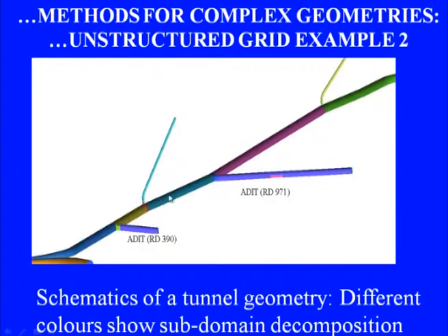And when we generate the mesh, if we are dealing with the straight tunnel portions we can go for structured hexahedral generation, but when we come to the junction points here, it is impossible for us to generate a structured mesh or have a continuation of the structured mesh from both the sides. So, these are the areas where we would go for what we call unstructured tetrahedral meshes.